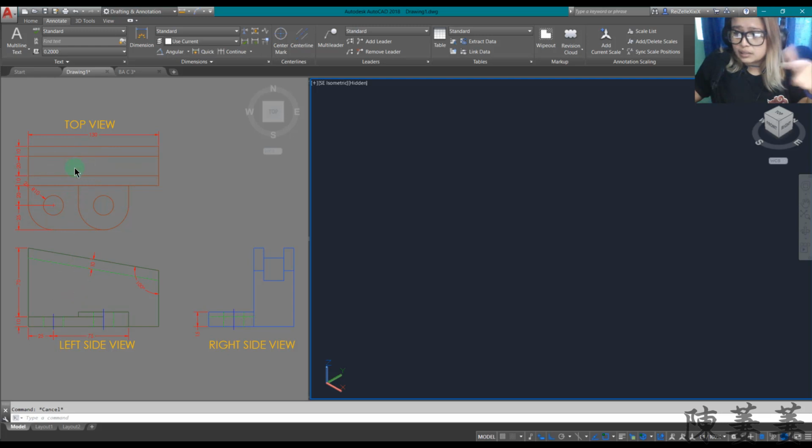However, as you can see on the orthographic views, it's much better to use the left side view, where you can easily 3D rotate the object to keep it upright, rather than create a solid base and then slice the object. So here we're going to use the left side view to create this part of the object.